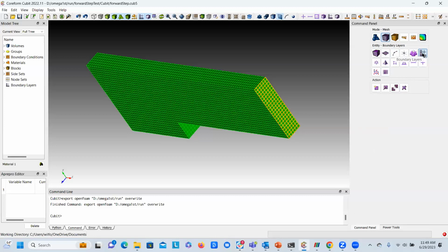So now what you can do is go in there and identify which walls need to have boundary layers attached to them and attach those. And it will give you the flexibility of putting in a fine grid that sort of grows away from that boundary, okay? So does that answer your question? If that doesn't answer your question, just feel free to type a follow-up into the Q&A too.